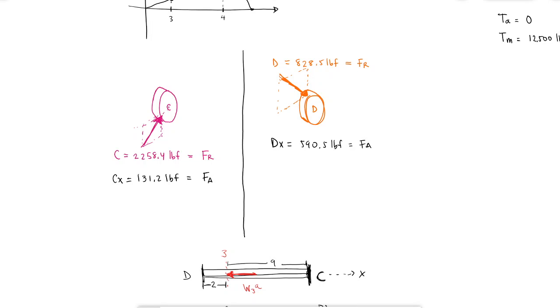What do you do with those? You combine them. You do the axial force over C0 to go into the table and calculate an E, to see if Fa over VFr is higher than E, and then use the equation to combine these into an equivalent load, so that you can look up a rated force and compare it to what the catalog number gives you.